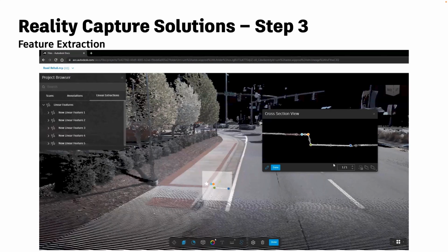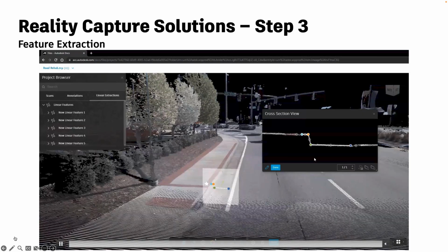Once you set up the proper feature codes here, it will be exported along with that metadata information, so when it goes to your Civil 3D folks, they know exactly what they need to do, because it's exactly what it is. And those empty gray points you see are the places where you can create additional vertices if you want to, more than 4, or if you don't want to, you can delete them as well. So you have complete control in setting up this template for the extraction.